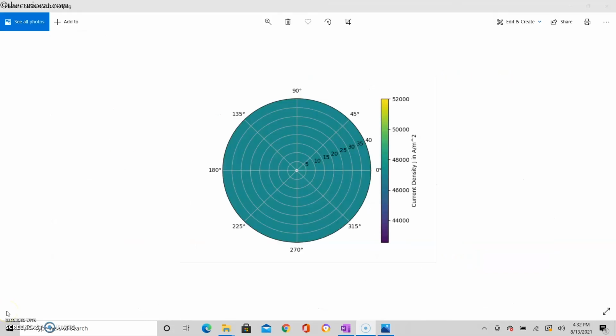To further demonstrate the skin effect, here is the cross-section of a copper conductor with a diameter of 0.2043 inches and carrying a current of 1 ampere at 0 Hz. We see that at 0 Hz, there is no skin effect because the current density distribution throughout the cross-section is constant. Now let's see what happens when we increase the frequency.